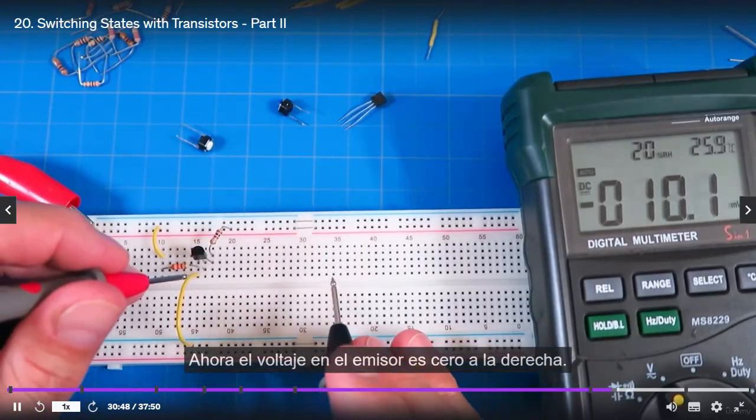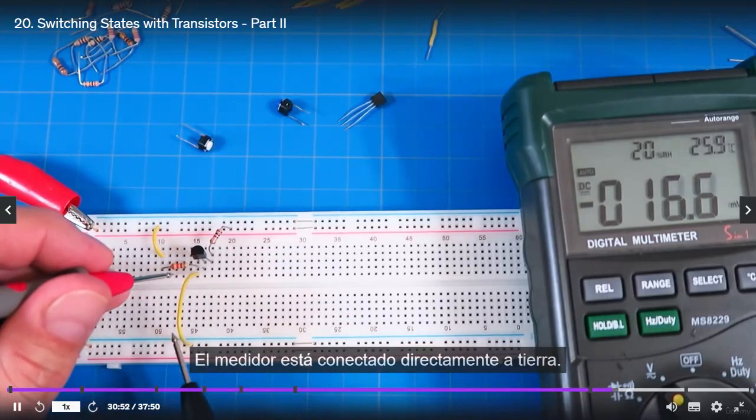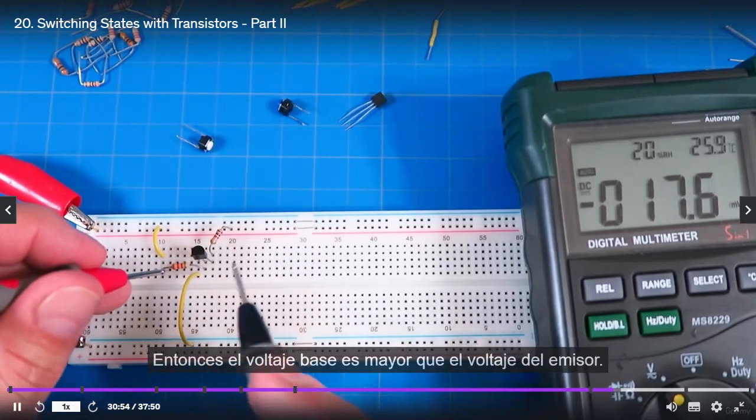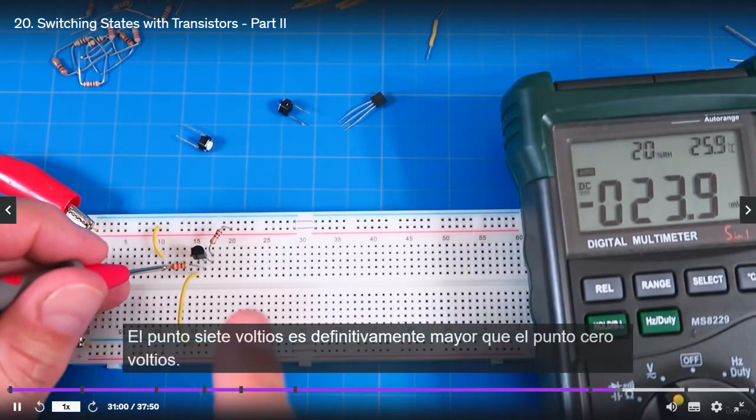Okay, so that's good. We forward biased it, so we know that that's going. Now, the voltage on the emitter is 0, right? The emitter is connected directly to ground. So the base voltage is greater than the emitter voltage. That's one of the constraints for being in the saturated mode. 0.7 volts is definitely greater than 0.0 volts.